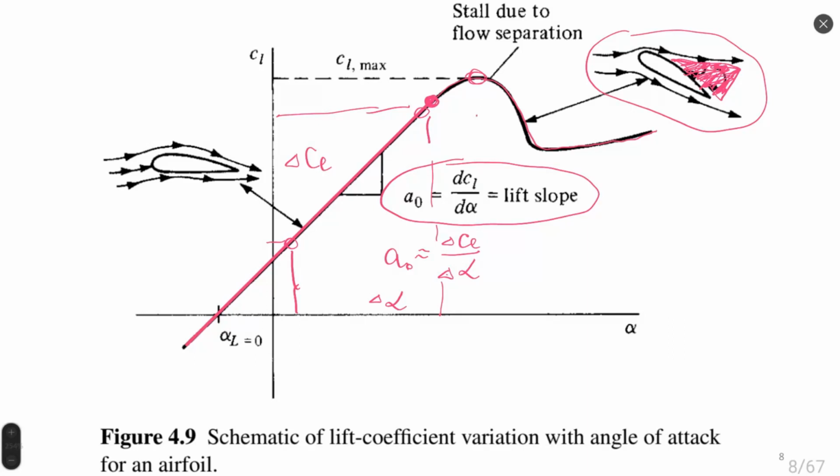Okay, and then there are also other characteristics. For example, the lift coefficient at zero angle of attack. It corresponds to Vmax, the maximum velocity of flight. So somewhere near this zone, we also see the maximum of the lift to drag ratio. So this point exactly corresponds to maximum velocity.